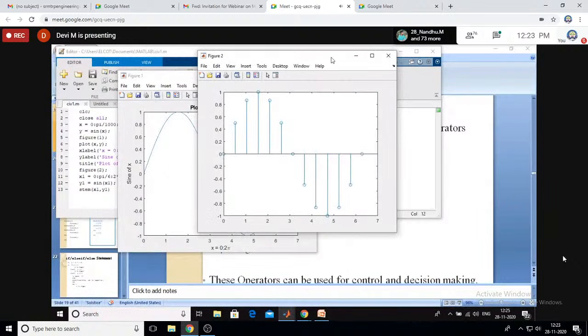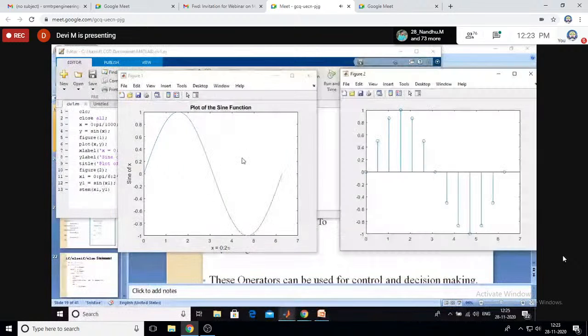Okay, that's it. So here I have generated 0 to 360 degrees with amplitude 1, and here it is generated for 0 to 360 degrees. Here I have used my stem plot to indicate the values at 30 degree intervals. I have given pi by 6, 180 divided by 6, which is 30 degrees. So sine 0, sine 30, sine 60, sine 90, 120, 150, 180. If you keep your cursor over here, it will display the value, but presently it takes time to display. I'll be moving over here.